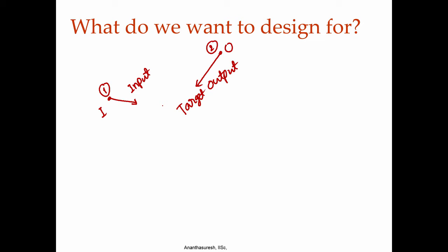instantaneously, meaning when you start applying force in a compliant mechanism, we would know the directions of the velocities, because you are applying input in the direction, target output in one direction, because when you say a point has to move, you want to apply force in that direction and you want target output displacement, this will be the displacement in a particular direction. So, when you have these two, we can actually apply that instant center concept. In between what is there has to be rigid for this thing to work. Now, we do not have a rigid body, yet instantaneously the concept works. That is the basis for the instant center method.